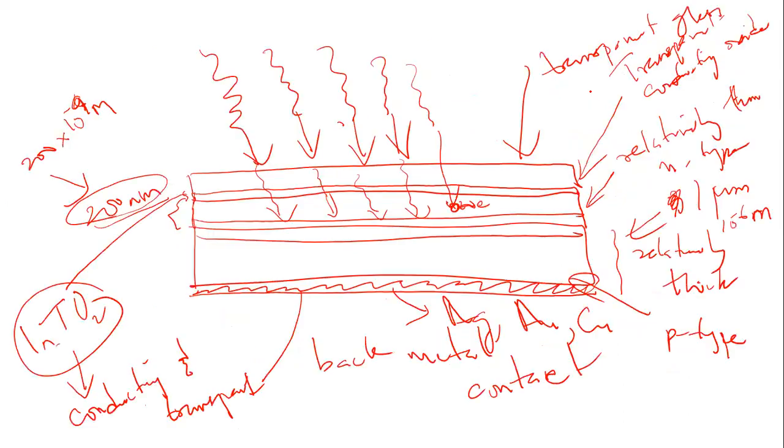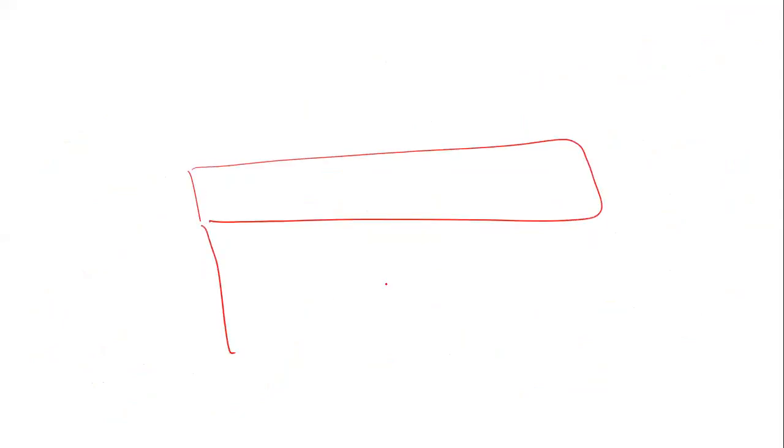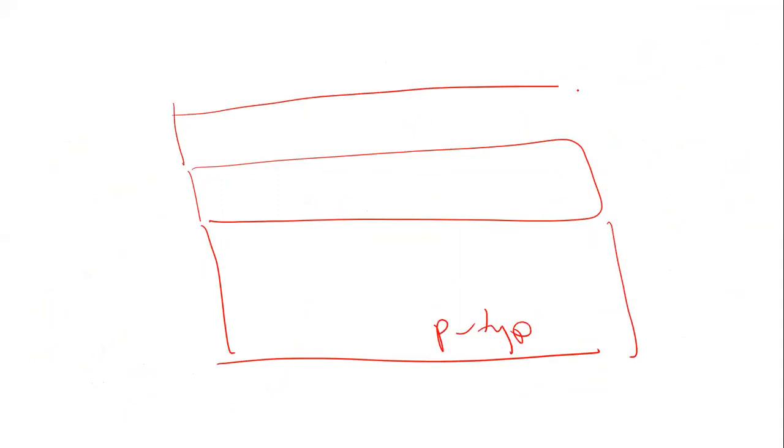So the electron hole pair formed within this n-type will not be able to contribute to your solar electrical energy. But when light falls on the depletion layer, let's say this is your depletion layer, let's say this is your thick p-type, let's say this is your thin n-type. When light falls on the depletion layer here, absorption also will result in electron hole pair formation.